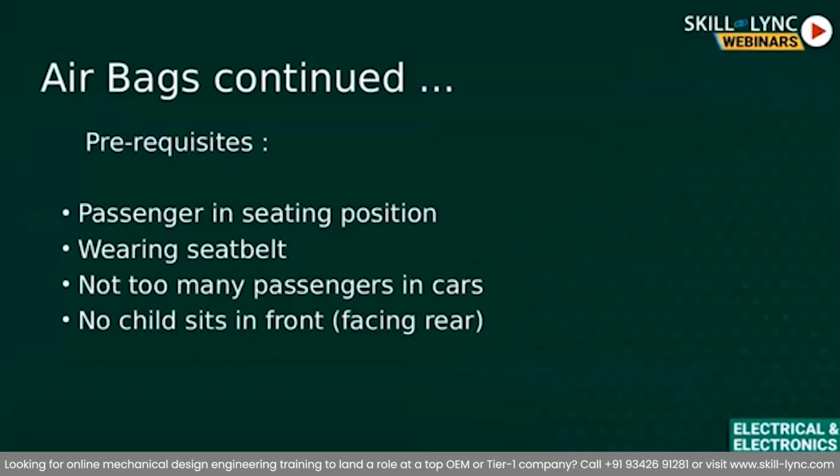Now you must understand airbags are designed for adults. When you have child sitting in the front, the position of airbag will not be effective in saving the life of child. And another important point to notice is airbags will be deployed in a fraction of a second with a lot of force. So the force can hit the child and leave bruises, or it can even lead to suffocation. And due to these reasons, child can experience severe damage.